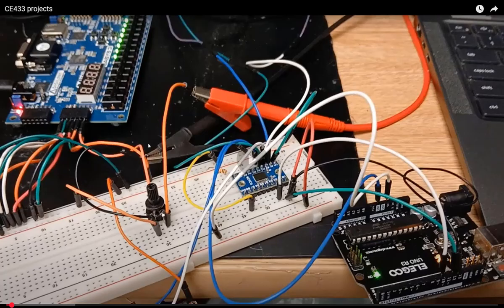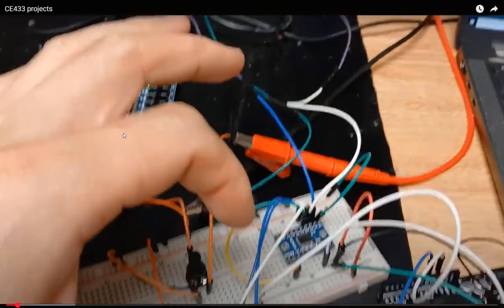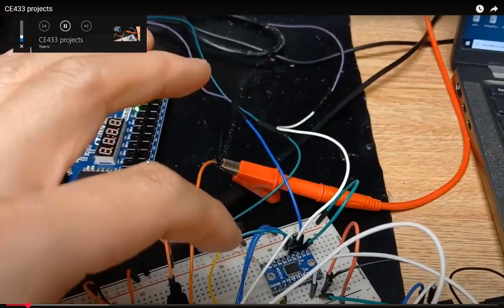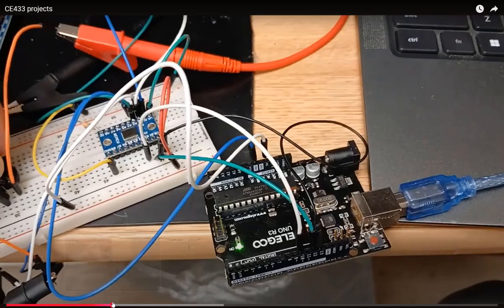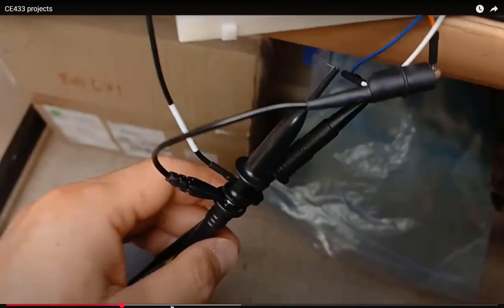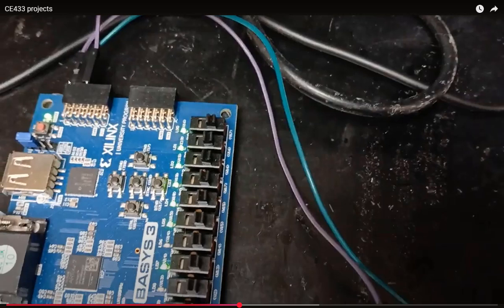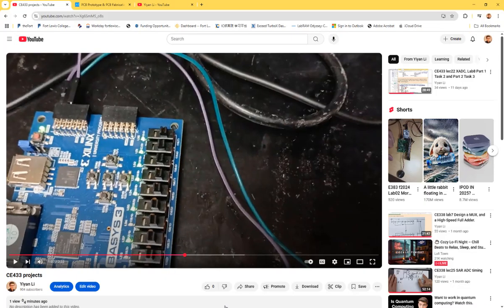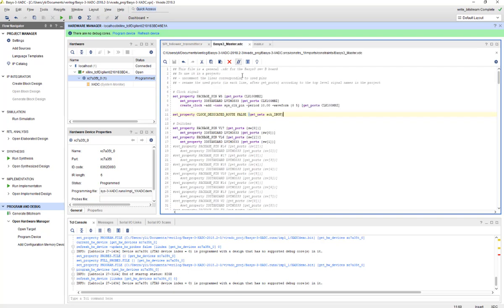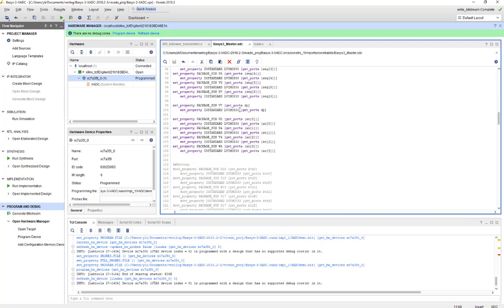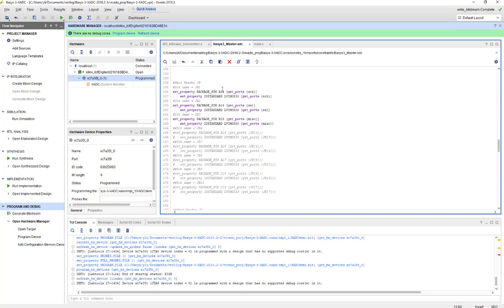And I used the JB pins. It's a different level shifter, and this level shifter is arguably a little bit faster than the one in the picture. The LEDs are able to display. So the JB pins, depending on how you want to modify your constraint file. So what I did over here is I changed JB0 to SCK, JB1 to SS, and JB2 to MISO.